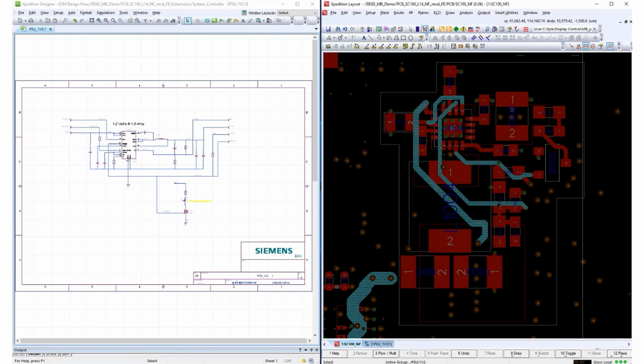The power supply on this board is replicated 4 times with different voltages. We have a proven power supply and a similar design already in production that can be reused. For this reason, we are going to create a managed block for the power supply, which allows it to be treated like a library element that can be used across many different designs.